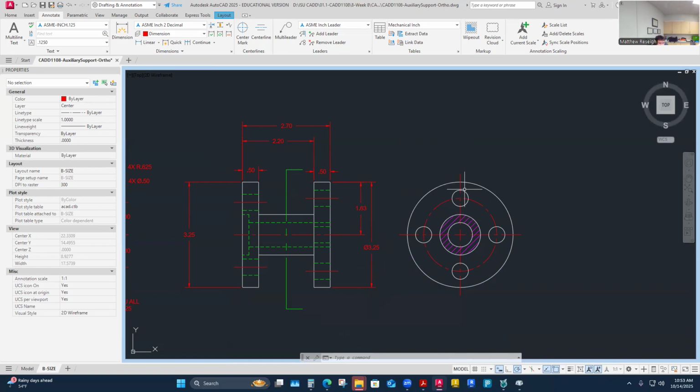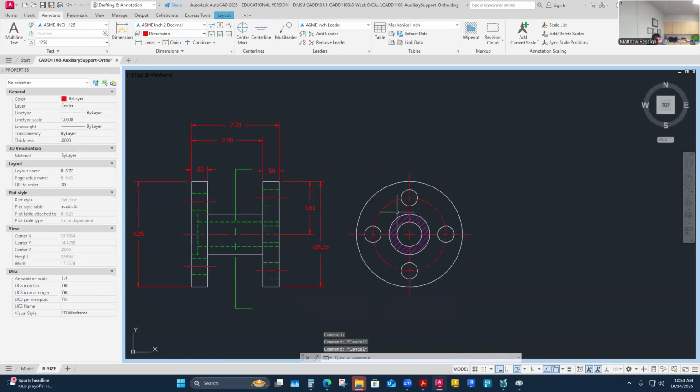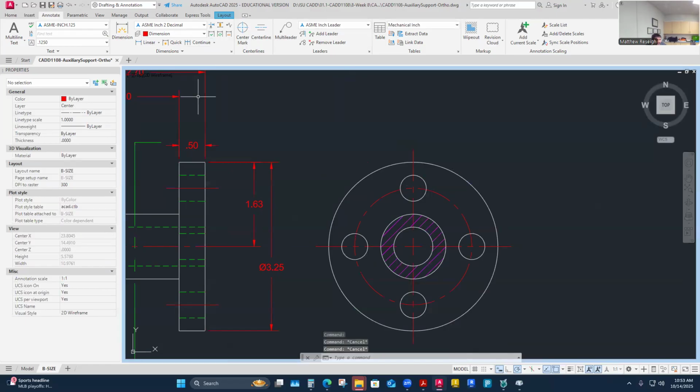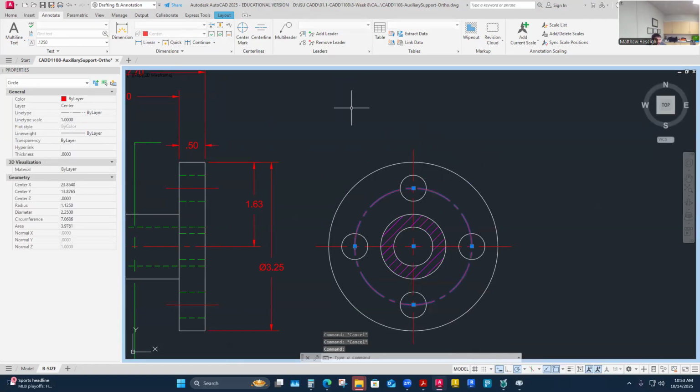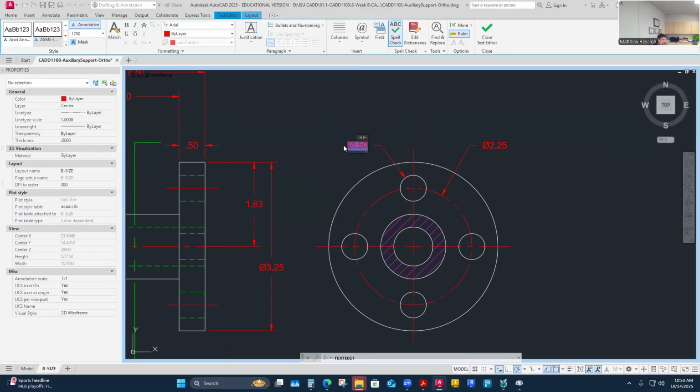Now I'm going to do some of its features, the holes. I think I can easily size those here. I for sure have they are based off of this bolt circle. So let's say I need a diameter on that. I need to call out what they're based off of. That's their location. Let's think of their size first. Size is still diameter maybe here and four of those things. So now I'm taking care of their size. 4x.